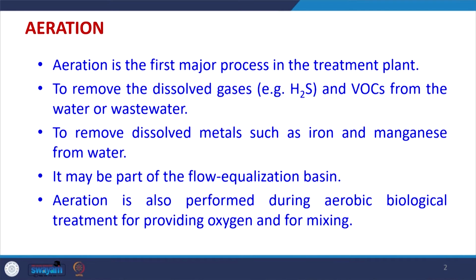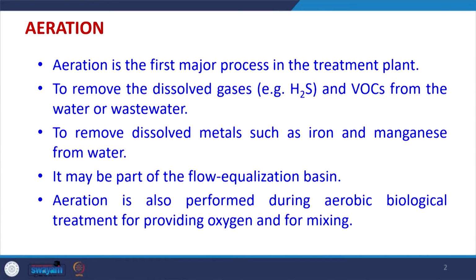So, why do we require aeration, and where is it used? In the treatment plant, aeration is one of the first major processes. It may be used individually, and it may also be in the flow equalization basin, if it is part of inline flow equalization. Aeration is used to remove dissolved gases. Many types of gases like H2S, ammonia, chlorine etcetera may be present in higher amounts if the water is being taken from the ground.